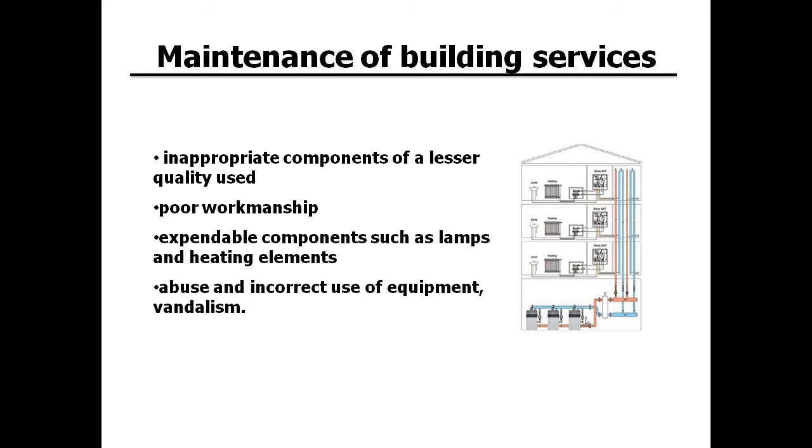Now, if we consider the services of the building, there's a number of things that we should and must consider there as well, to ensure there's continuity in the organisation or the tenant or the building providing the service that it's intended. So with building services, we need to look at things such as accessing the services for repair, for replacement. I know of cases where walls have had to be demolished and large excavations made to get chillers out of basements for replacement at the end of a 20-year period.